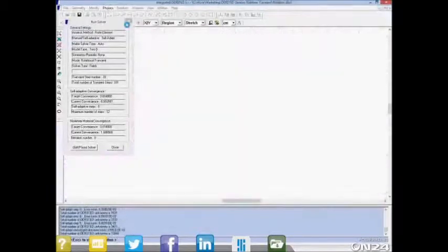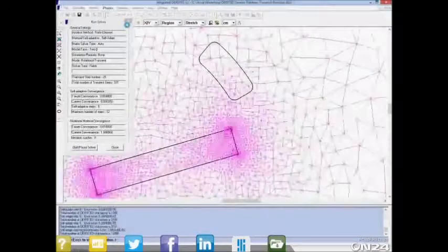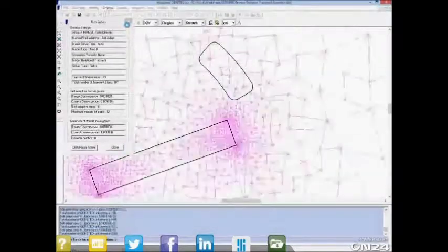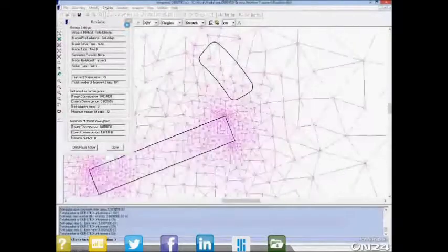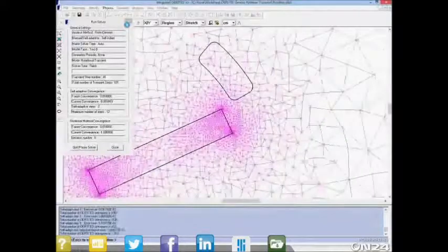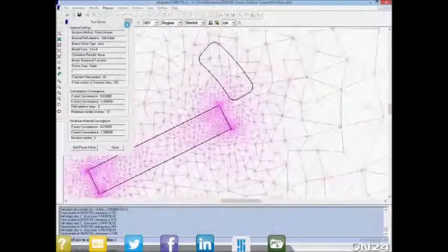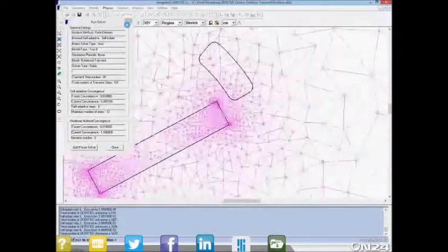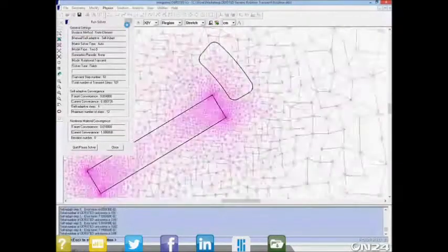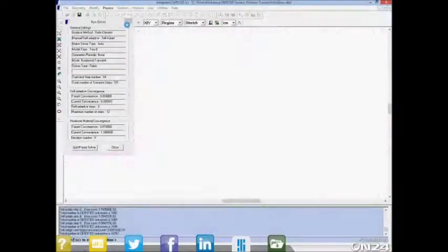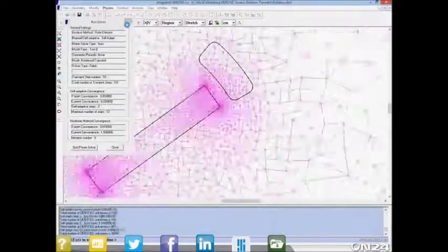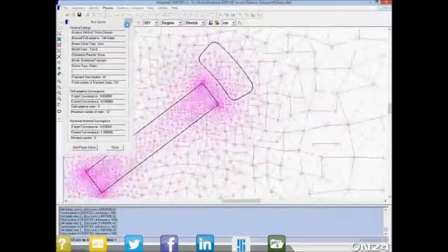And what you see happening here is that every time we rotate the magnet, of course, a new mesh has to be created. So as the solver proceeds, we're seeing the mesh updating. And as the magnet approaches the aluminum, you'll see that the mesh starts getting denser in the aluminum because we'll start seeing more substantial flux changes in the aluminum, d-flux by d-time, and therefore the mesh will need to get much denser there.